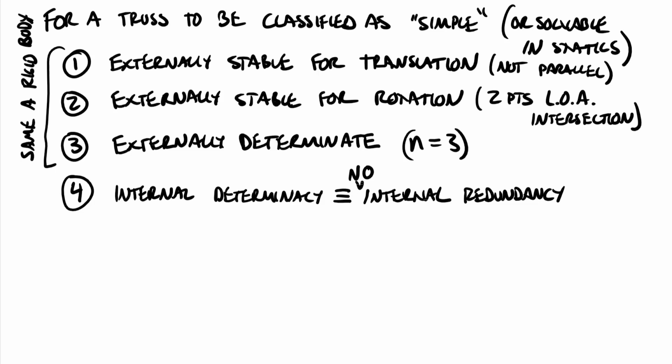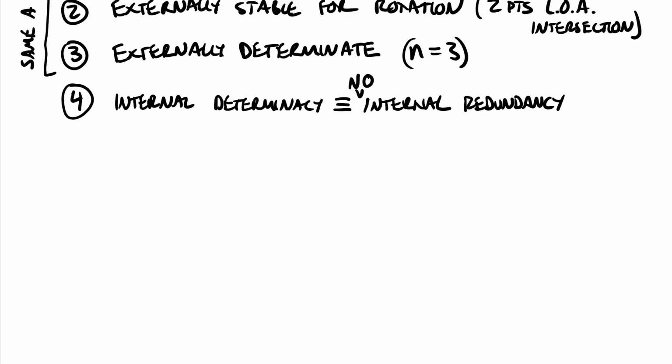Now, redundancy in engineering design is not necessarily a bad thing. Okay, if one structural member breaks, another structural member could step in and do the work of both of them. That's not a bad design plan. But here in statics, we actually don't have enough equations to handle redundancy on the inside of trusses. Okay, so we're going to be stuck building these or analyzing these simple truss systems, which to be honest, some people call fracture critical trusses, because if one single member breaks, the whole rest of the truss is actually going to collapse.